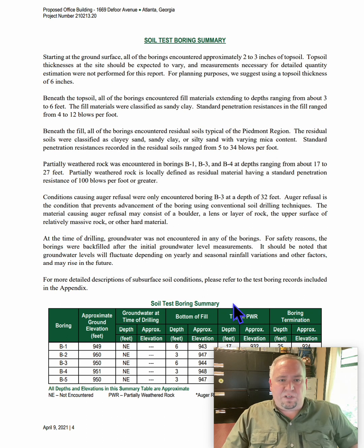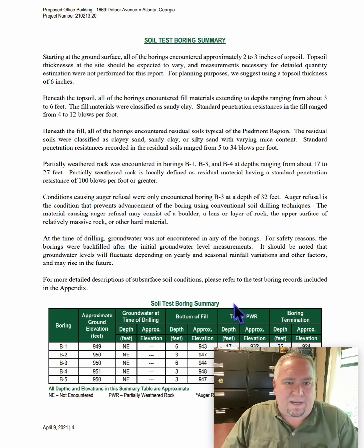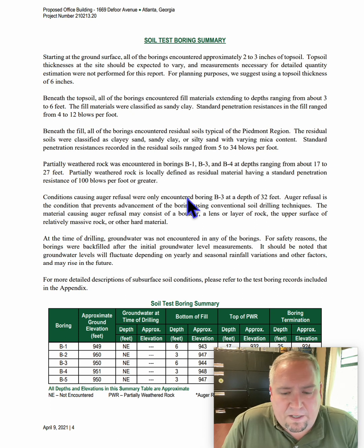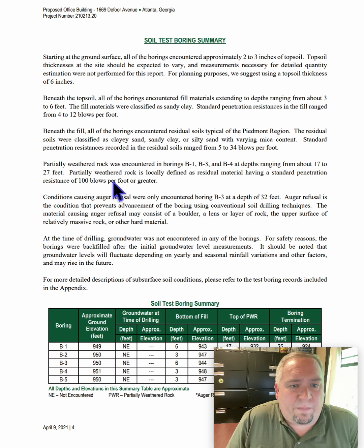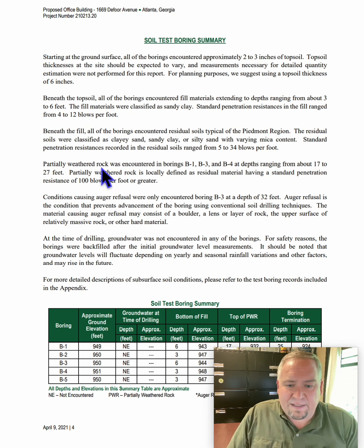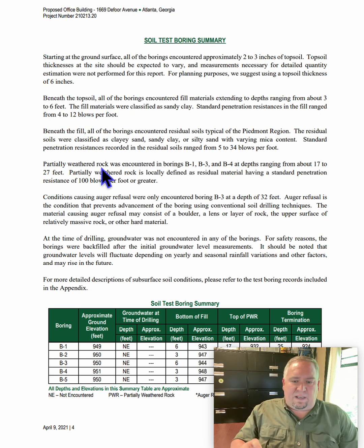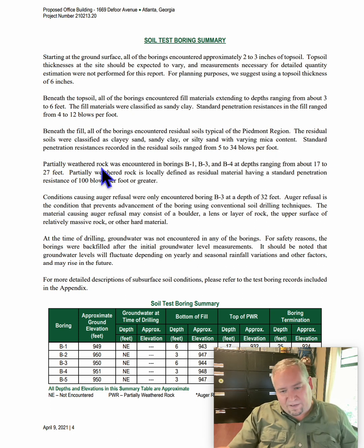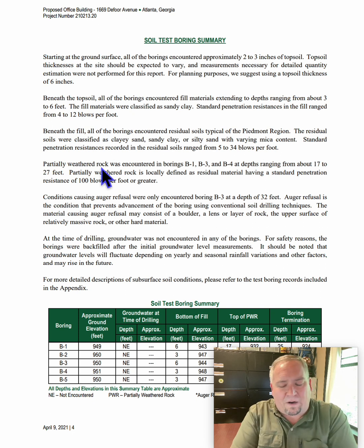They're just giving you a basic overview. You can read through these. They're pretty good to get a good understanding of what's happening. One of the things you're going to see quite often is partially weathered rock. That is essentially, if you took an excavator, say a 200 series, and you can scrape it with your teeth and it would almost chip out, and you can grab it by the grain and pull it out without breaking the bucket, that's called PWR.